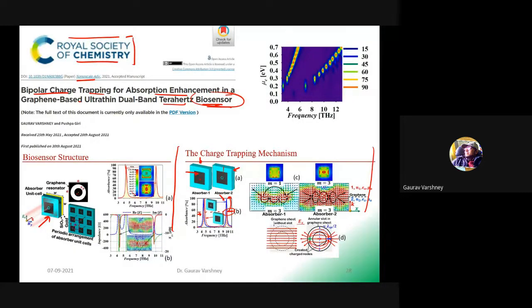If we do not place the annular geometry at the center, then the surface plasmons generated at the graphene-air interface have mode index 1, and at the bottom dielectric-graphene interface it was mode index 3, a half wave variation, a single half wave variation.